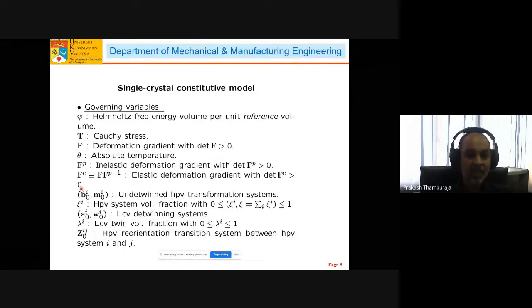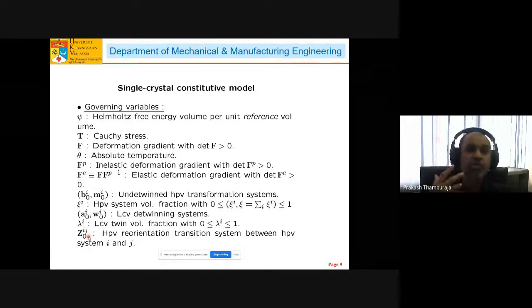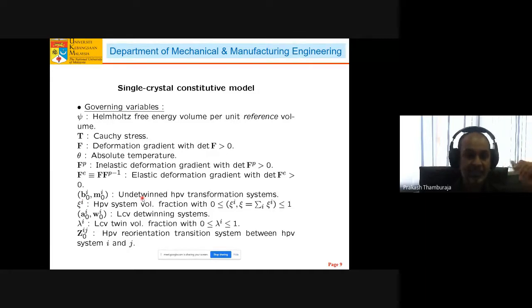Finally, you also need to have some kind of description for the change of microstructure in the body due to twinning. That is all obtained from crystallographic theory, which is called the phenomenological theory of martensitic transformation. You can use geometry to calculate the crystal lattice vectors and all that quite simply, using just basic mathematics. You can also use experimental analysis, but it's a bit more arduous. So we've used mathematics to calculate the twin plane vectors, the twin plane normals, the shear directions, and so on and so forth. We've used the theory to do so.